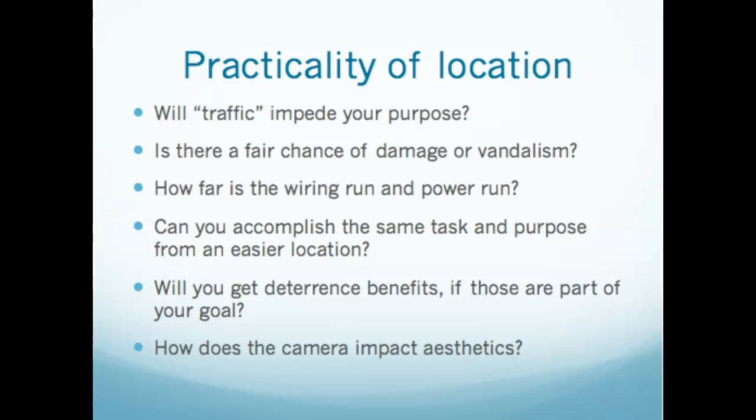Is there a chance of damage or vandalism? Normally, you want to have your cameras up a little bit, so cameras are not real great when somebody hits them with an aluminum baseball bat. They're rugged, and those domes are really made ruggedized now, where you can hit them. You can buy them where you really can hit them with a bat or a crowbar, and you'd really have to smack them. They make them bulletproof, but quite frankly, it doesn't take much. Once you start hitting the housing, something's going to give. And so if you think that the camera might be vandalized, you want to put it up a little bit higher, right? Is it practical to put it down low where you really want to look at somebody's face when that person can then manipulate the camera right in front of them?